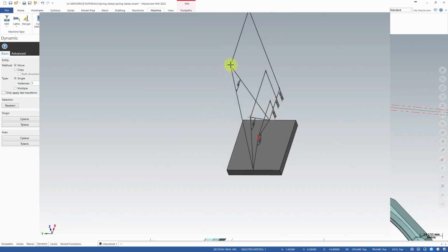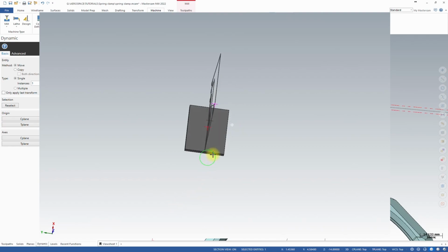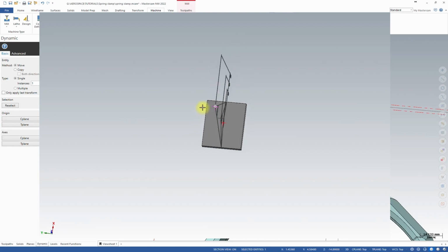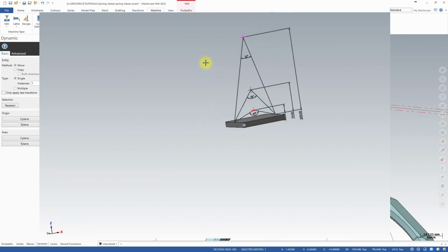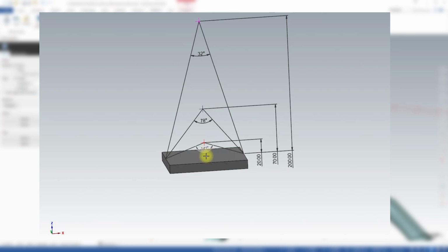But if I grab this one, that is 200 mil away, the changes are not big at all. It's just a small move, small motion, small tilt action. Okay, so generally if you want to use tool axis control from point, if you don't have to be close to the surface, go as far as possible.